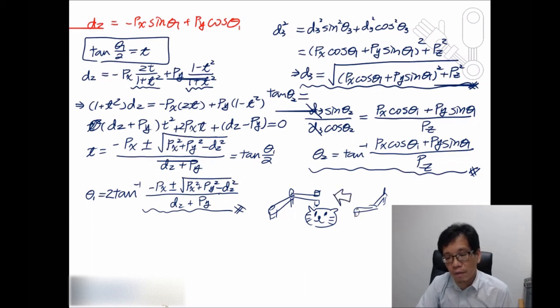Yes, configuration-wise, it's possible, but realistically, this might not be feasible because all of a sudden you want this joint to jump from this position into this position. You might have some kind of vibration problem, or it's totally impossible. So when you are designing the trajectories, you need to be careful, use the correct explanation and correct configuration so that individual joints can be derived accordingly.